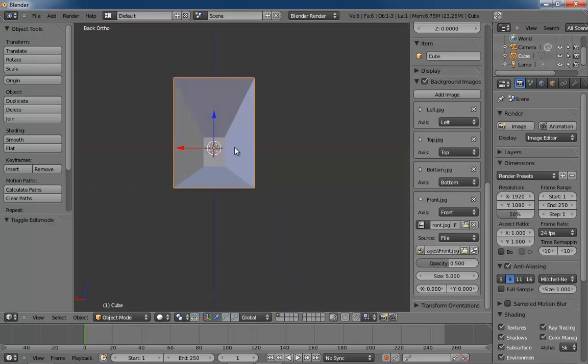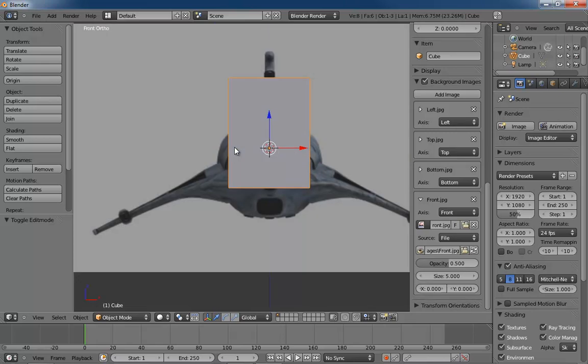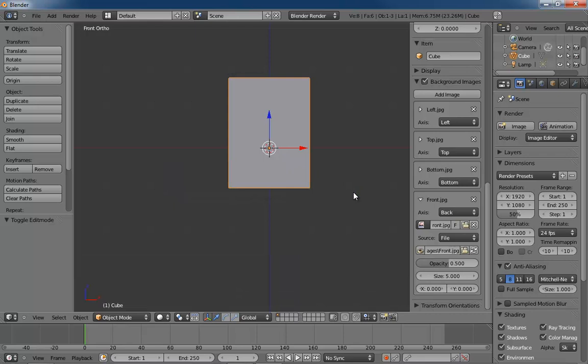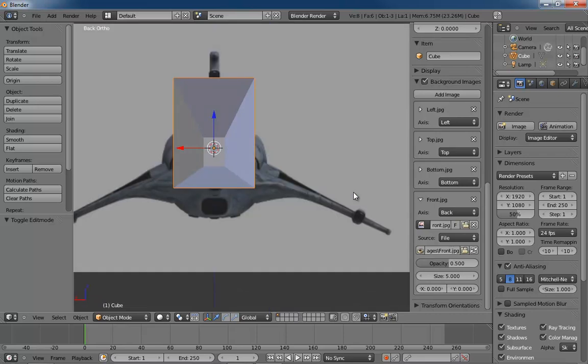So the front and the back are, well, the way that you would think about them are reversed, if you'd be actually looking toward the direction of the front and not at the actual front of the object. What does this mean to us? This means we need to reverse which images are shown where. What we're going to do is take our front image and associate that with the back camera. So now if I hit Control, boom, that's going to flip around.